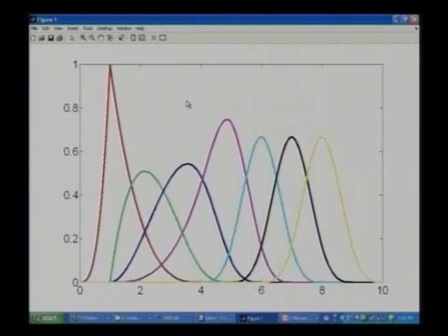The B-Spline basis functions change in shape locally. Now, if you realize, at this knot value 1, the first B-Spline basis function has the value 1, and all the others have the value 0. This concurs with the local barycentric property.